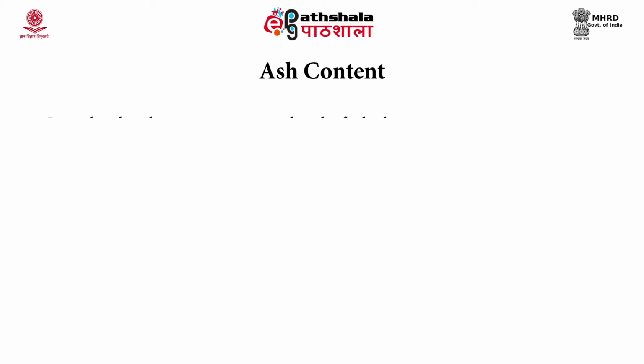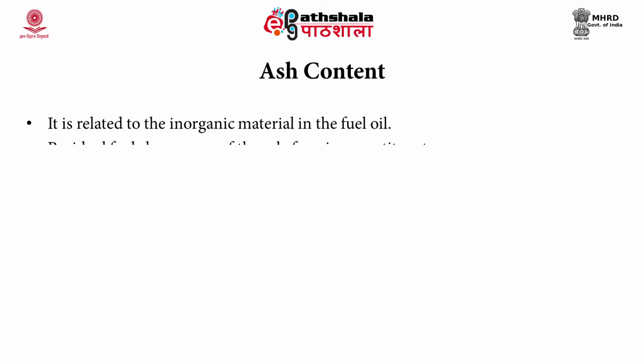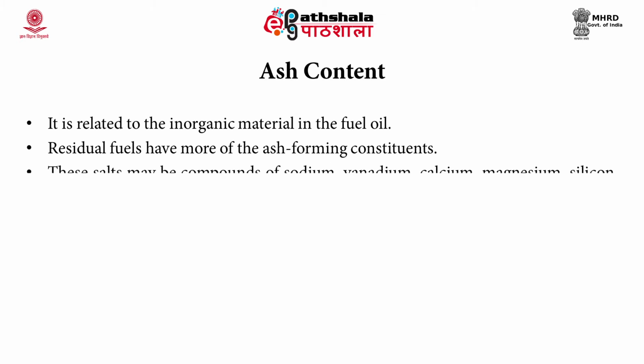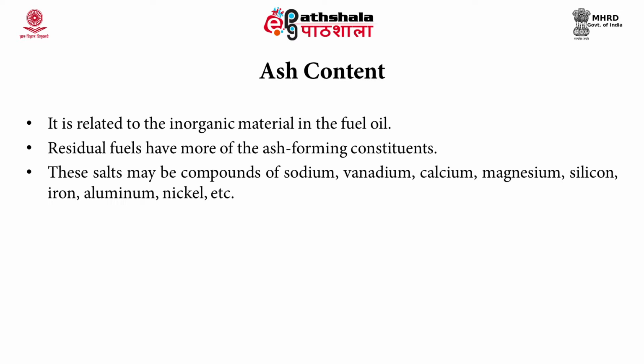Ash content is related to the inorganic material present in the fuel oil. Residual fuel has more ash-forming constituents. These include compounds of sodium, vanadium, calcium, magnesium, silicon, iron, aluminium, nickel, etc. The ash value is normally in the range of 0.03 to 0.7%.